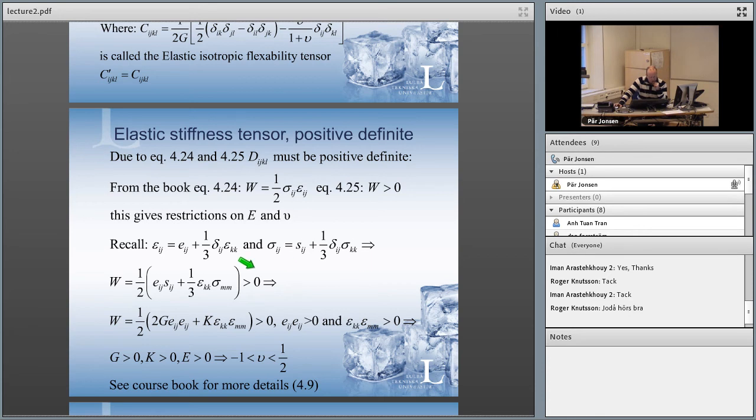But if you now look, we had some restriction already on Young's modulus and Poisson ratio. But can we get something more out of it? So if you remember, you can write the strain tensor like this, using the deviatoric strain tensor plus the trace in the system. Calculate that one and set it into the tensor itself. And the same for the stress tensor part. You are using the deviatoric part. This is a way of rewriting your equation. This is just a relation that holds.